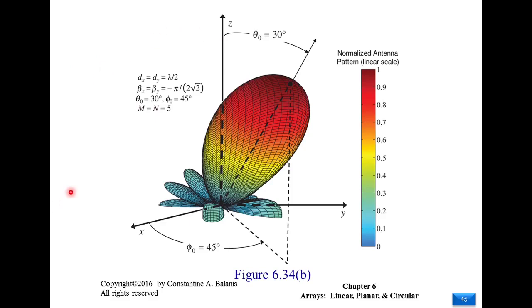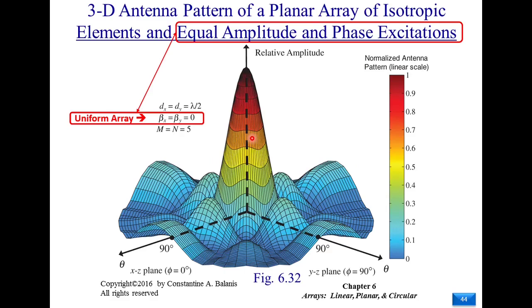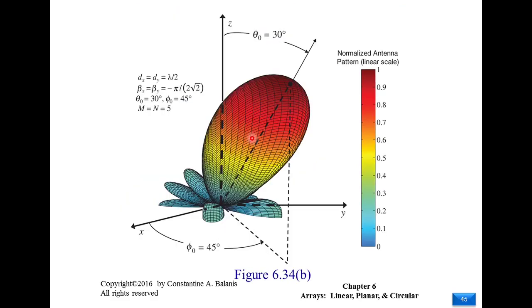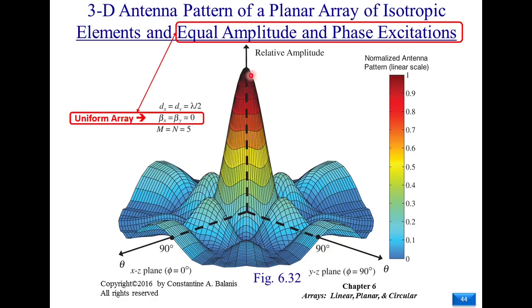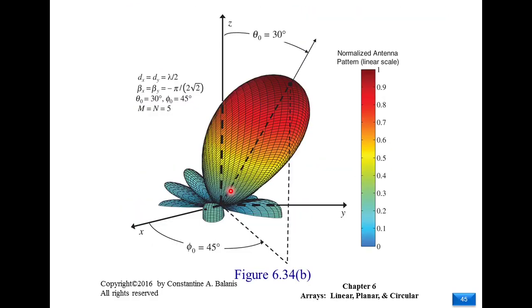Just to have a feeling. And you can notice easily that the shape of the main beam is different between the two cases, and this is very expected. When we go off the peak, the main beam will also change its shape, not just the direction. Its direction and shape will be changing.